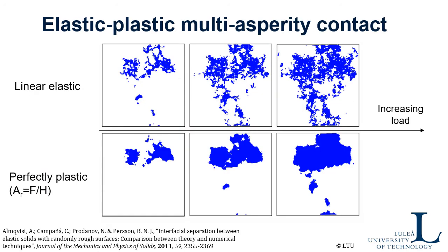So, is this true then? Is it useful to use that law? Well, here you can see some example where we have been doing a more exact computing of the contact area, and we can use contact mechanics theory to solve the linear elastic contact of a rough surface. So here you see that by increasing the load, the blue spots represent the contact spots.